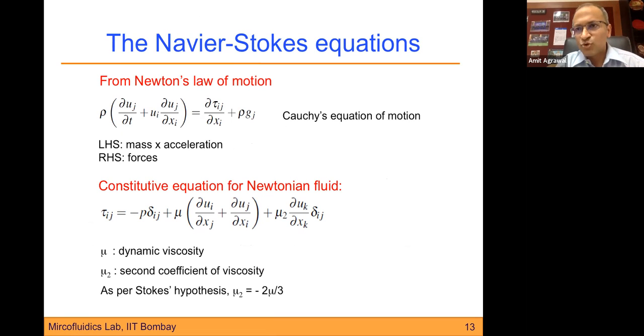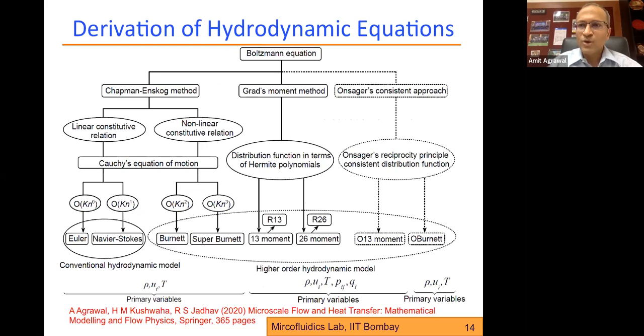But now, if we were to follow this approach, and we say that on one hand, there's something which is missing in the Navier-Stokes. This is how we derive the Navier-Stokes, and there is nothing wrong with this approach, and there is nothing else that we could get other than the Navier-Stokes equations. So then, how do we reconcile the two things? How do we see that there could be additional terms introduced into the equation that we are not seeing in our approach? That means that the control volume based approach that we have right now is not good enough. Although we do get the Navier-Stokes equation that way, we cannot do anything beyond that.